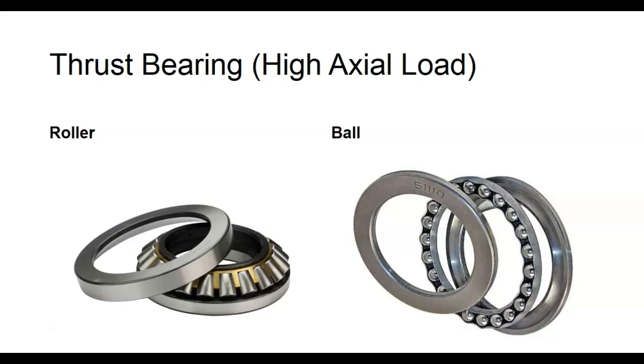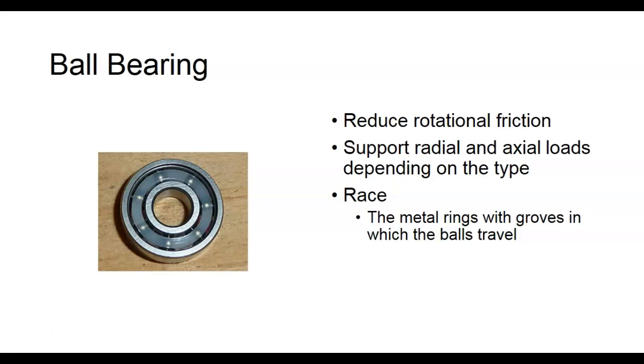Instead of the ball being mounted this way, they're mounted regularly. And the races, instead of being out, the races are on the inside. And you can see this too. They don't show that, but this is very popular, where they'll come in and put a covering over the actual bearings itself. A lot of times they'll be metal. And then what they'll do is they'll put grease or oil in there, and it'll last a lifetime.